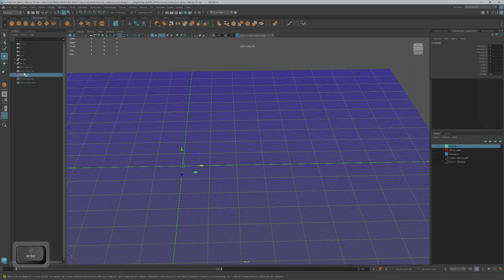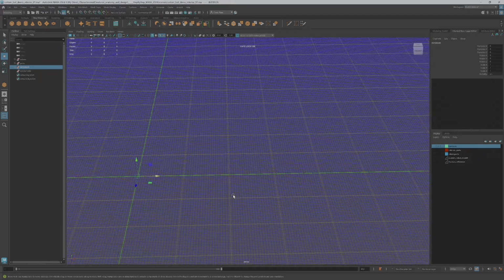And then for the doors, I'll group that and we'll say furniture. Or actually the doors should stay with the interior as well. We'll grab these doors and middle mouse drag them into the interior. And then with this group here, we'll call this furniture. So I have furniture and interior as a group. I also have furniture and interior as layers, so channel layers that are color coded as well.